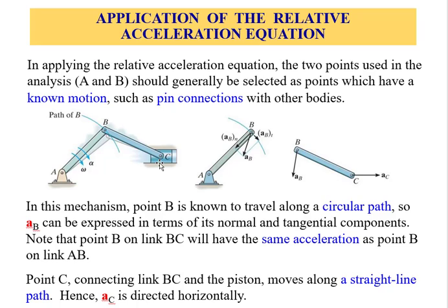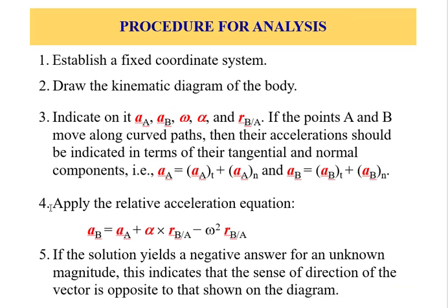So to find the omega, you have to use the relative motion analysis of the velocity to help you with omega, or you can use the IC, instantaneous center of zero velocity, to calculate omega, as we discussed previously. That can be found by constructing normal lines orthogonal to the path or the velocity, and then the IC will be somewhere here, and then we use the geometry and calculate the omega, knowing that the velocity of the point B can be found from this link. All right, so that in a nutshell is the process applied to that example.